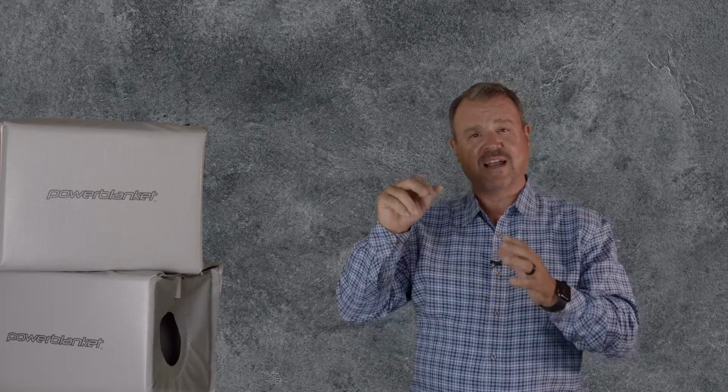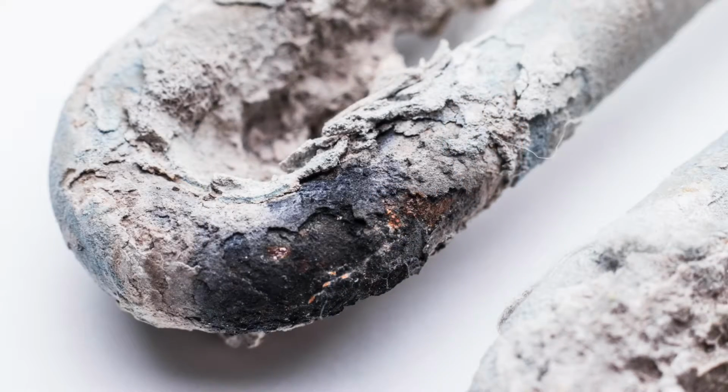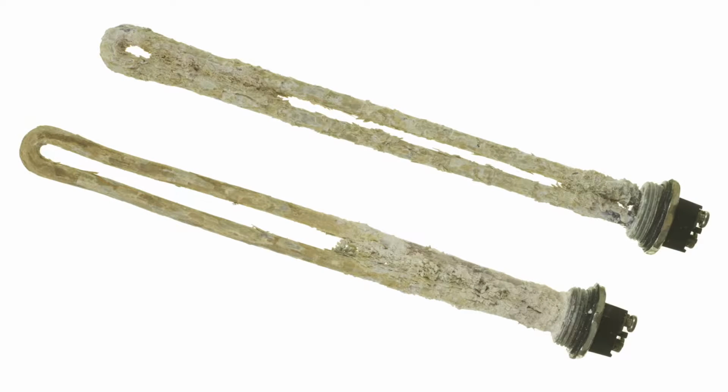I've seen electric heaters in process for over 30 years, but I've seen some that have gone out in 1 year. Electric process heaters can get attacked by corrosives because the heating element itself is the hottest portion of the process. The hottest portion is always the part that gets attacked first. So corrosion is a big issue with electric heaters, and you can't always see corrosion in electric process heaters. It occurs inside of the process.